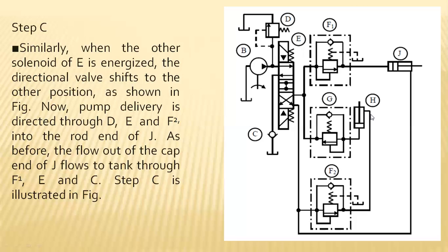And next, at this particular point, the backward movement will commence, and the piston will start moving from the rod end to the piston end. At this particular section, the highest pressure is entering here. So to cause the slowest motion, the position of the check valve will be changed.